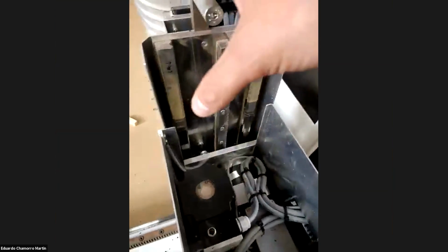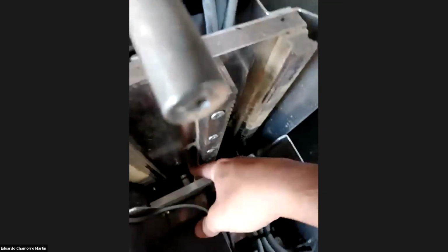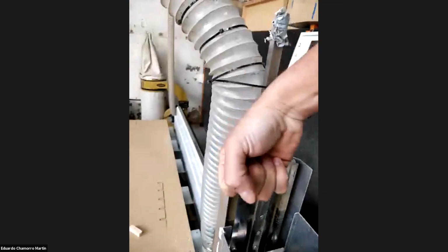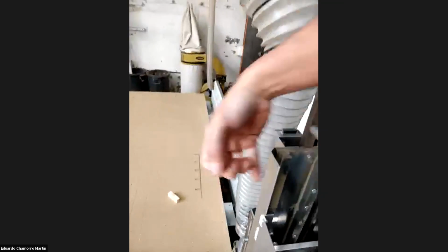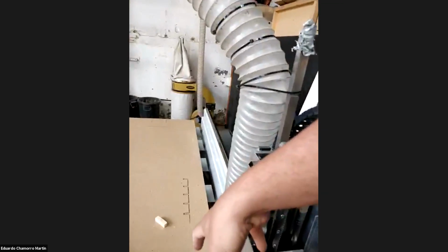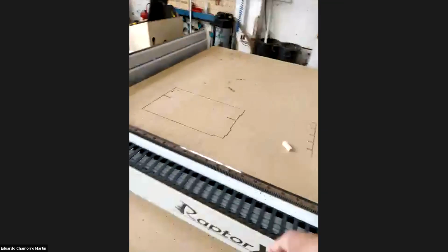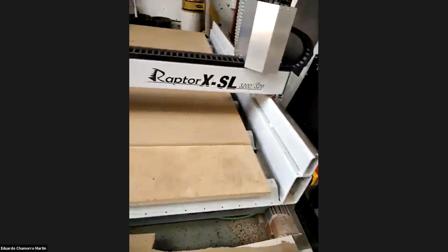As this is really heavy, usually the Z axis, we can see from the bottom. We don't see it now. But we have a spring that is also helping to keep the position, because this motor is quite heavy. So instead of having everything held by the motor, we have also a spring helping so the motor doesn't fall when we switch off the machine. You have to change it every now and then. The spring? Yes, but that means years of use.